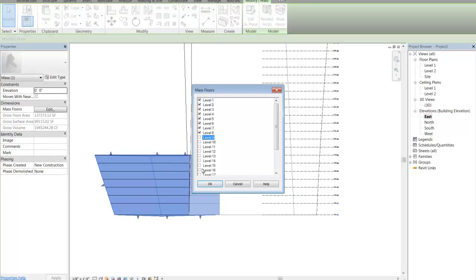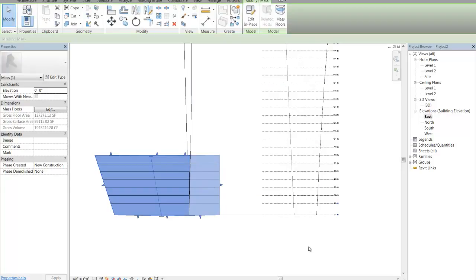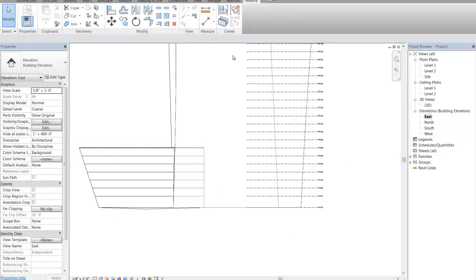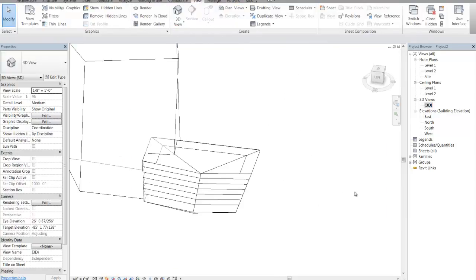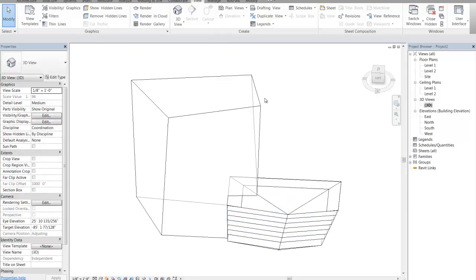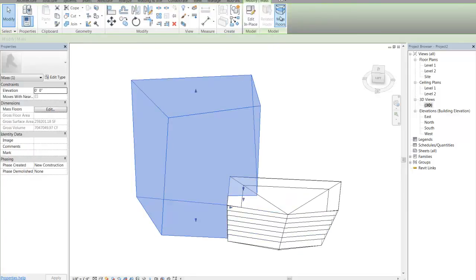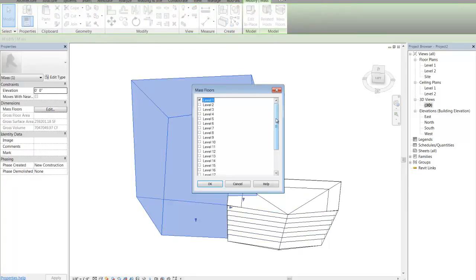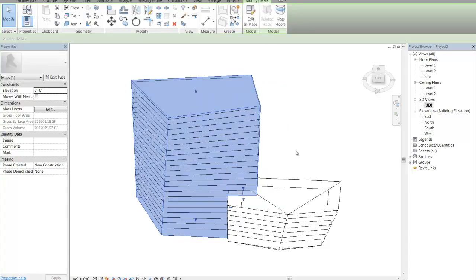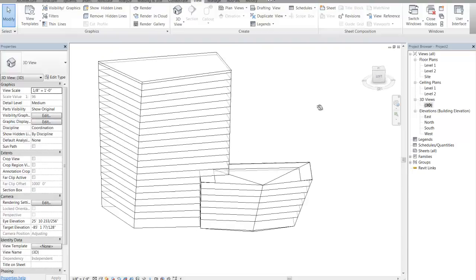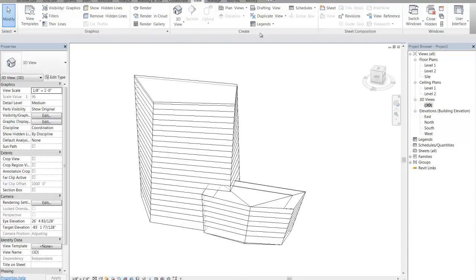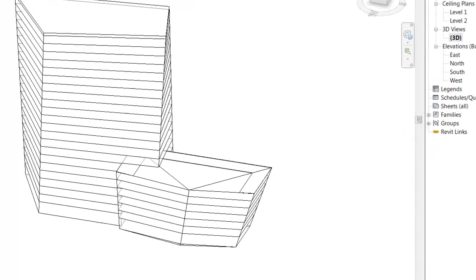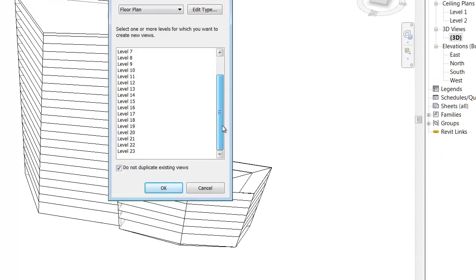I'm going to check that out. I'm going to get errors later on if I'm trying to create mass floors in a thing that doesn't sync up. So just popping in the 3D view here. I never finished the mass floors in the other tower. So we'll select all those. There we go. Okay, so basically what we set up is the same kind of setup that we've been using before. Again, if you want to make the plan views for all of those drawings, you can do that.